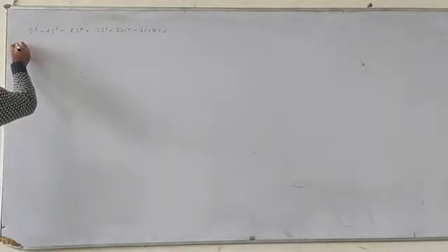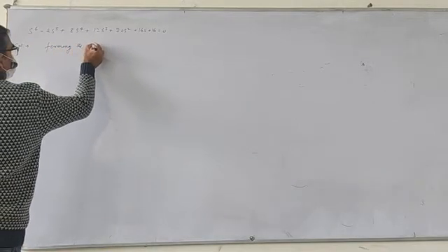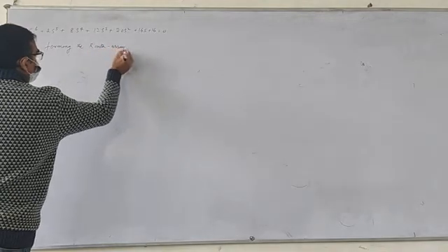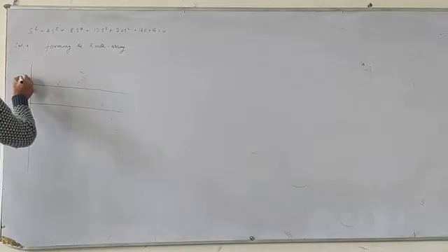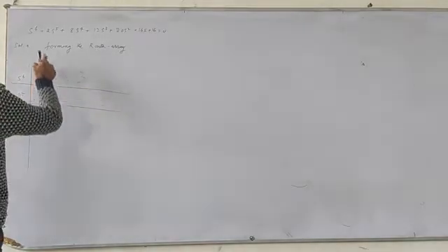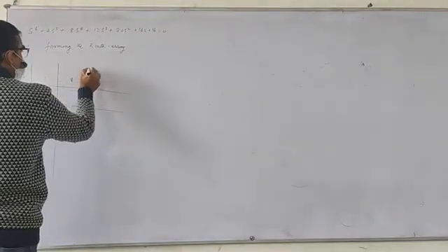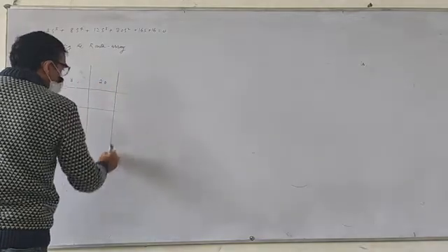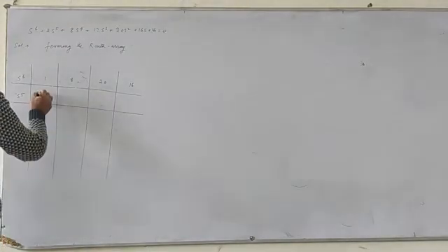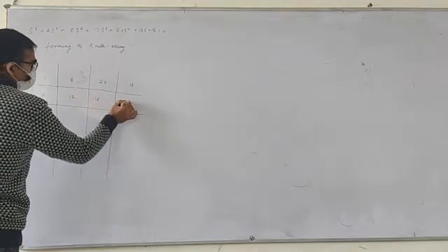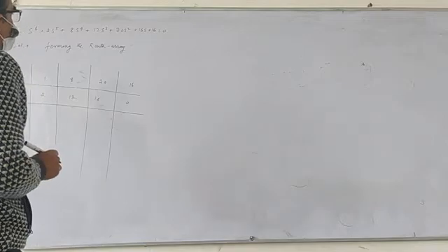So we'll form the Routh array. How have we formed the Routh array? We already discussed this. The first rule: the maximum power is s to the power 6, then s to the power 5. So the first row is 1, 8, 20 and 16, and the second row is 2, 12 and 16, and then 0.